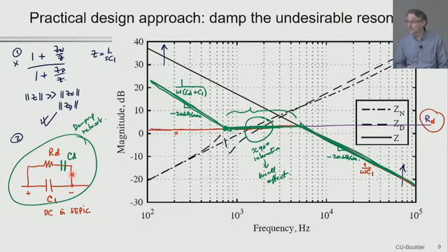Okay. So in the Zin and ZD plot, there is this thing at low frequency. So R should be chosen so that you avoid that region. Yeah, you may have some issues right here, right? There are more complexities here than we have explained so far. It is possible to choose things so that you hit a different type of interaction right here. So we want to stay away from that if we can.